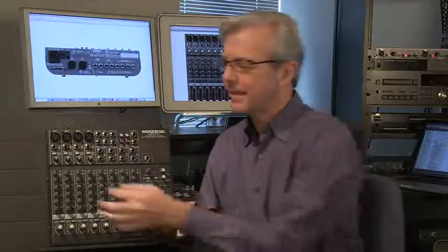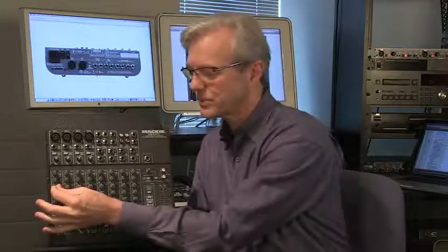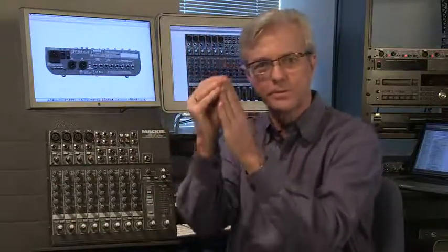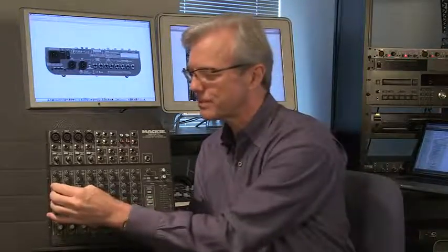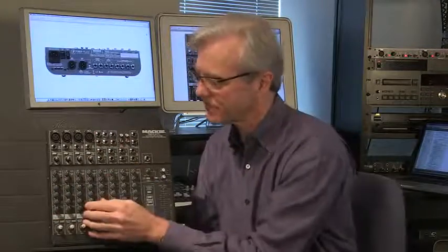So what the sound engineer would do is measure those points, and then on the parametric equalizer, they would specify those frequency points and then reduce those down so that you end up with a flat response, which is what they're trying to achieve. Every room has a different acoustical mapping to it. So the equalizer is important both for being able to, in our studio, adjust the sound in very nuanced ways, but also in sound reinforcement, it's critical in order to avoid feedback problems.